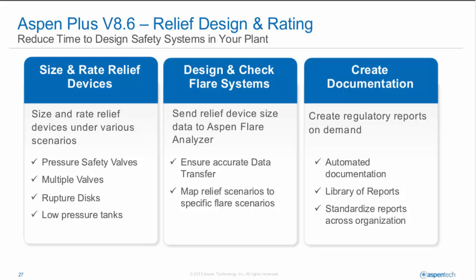Now, this new capability fills what was a gap in the workflow from coming up with the relief loads with a simulator and then downstream modeling the flare system. So the new pressure safety capability can read the conditions from the simulator, including the physical properties of the various streams, use that in the relief valve sizing, and then that information can be shared with the flare analysis tools, Aspen Flare Analyzer.